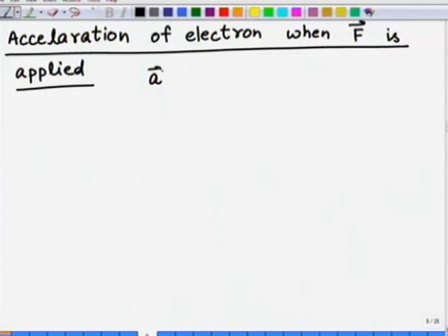The EK diagram gives me all the information through quantum mechanics, which is what I want to use, and then I want to reduce it back to a classical-like particle which follows F equal to ma, and hence my calculations will become easy. And so I am trying to fit that EK data into an F equal to ma type expression. All right, so let us do that. Acceleration, as before, we will define as dv dt, and we already know what v is.